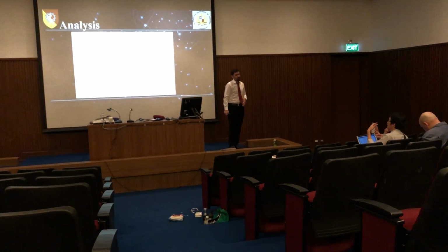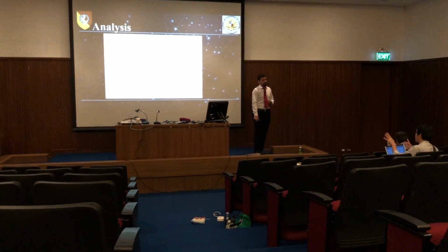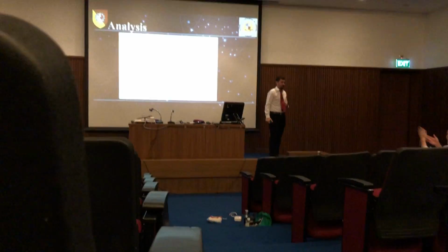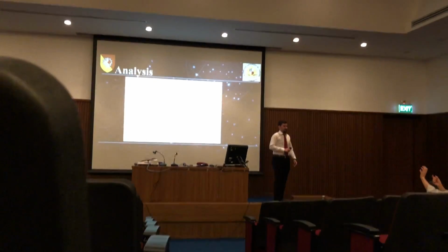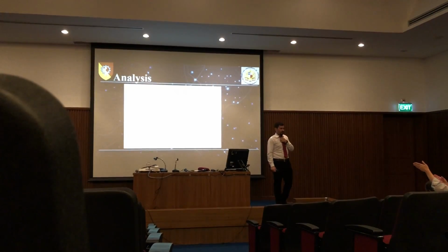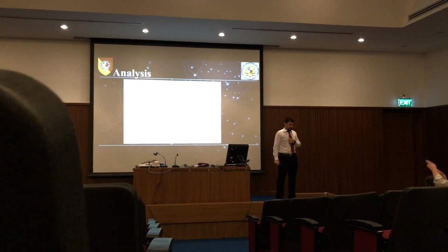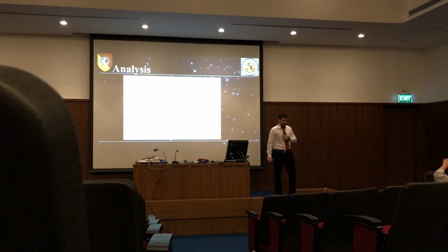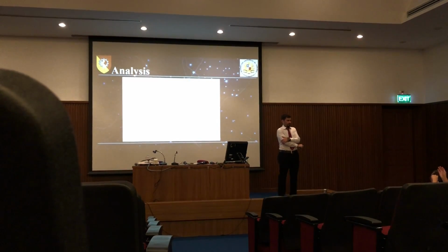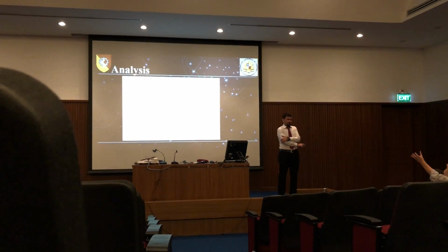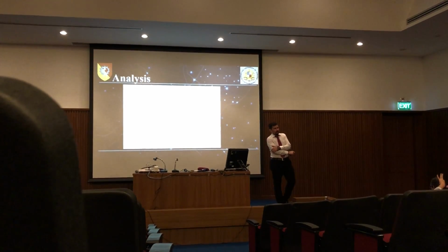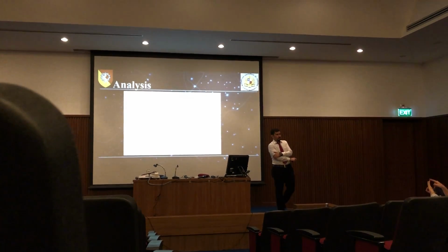Does it get dumped in characters, which means 8 bits, or words of 16, 32, 64? What's the clock rate over that device bus? And then the CPU reads that, or is it through DMA? Does it go into memory that's eMMC, or is it through the RAM? If it's RAM, then it's held in a buffer, right? And then you take the next frame and subtract it. So there's the electronic part: acquisition, frame 1, frame 2, subtraction.